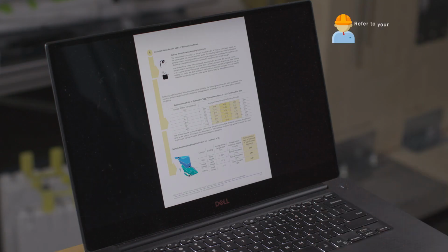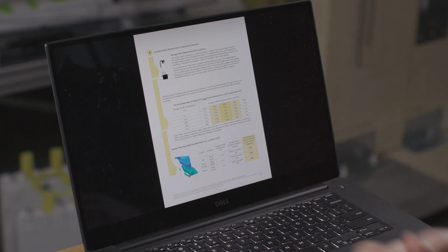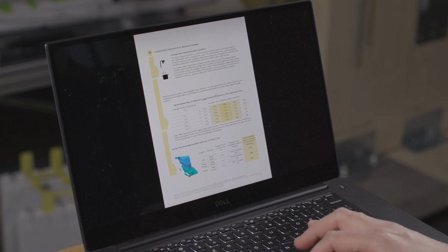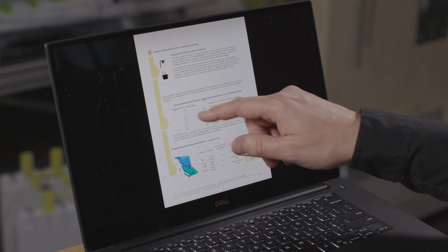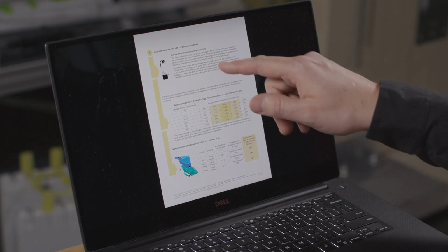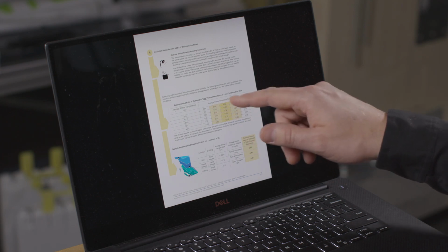And so when you follow through the building science discussion there, it then gets into some guidance. Okay, what ratio should I have, or what ratio would be safe for this wall assembly? If we look here, we have this table of ratio of outboard to total thermal resistance. Depending on where you are in Canada, you look at your average wintertime low temperature here. So say 0 degrees, and then you have an indoor wintertime humidity, generally in the 30 to 50% realm, depending on what you're designing for.